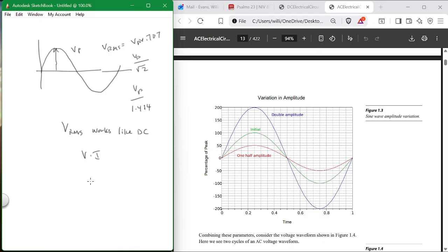Power is equal to, for VRMS, V times I. All right? And sometimes we just talk about voltage. I'll just do this. Here's my voltage supply, and it's 10 volts. Well, now is that, I'll say 10 V, and I'll do a little squiggly. Is that RMS or is that peak? We don't know.